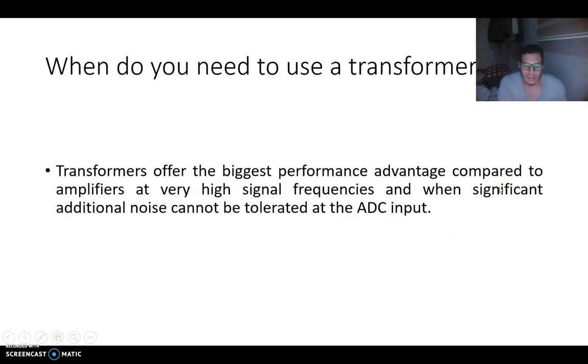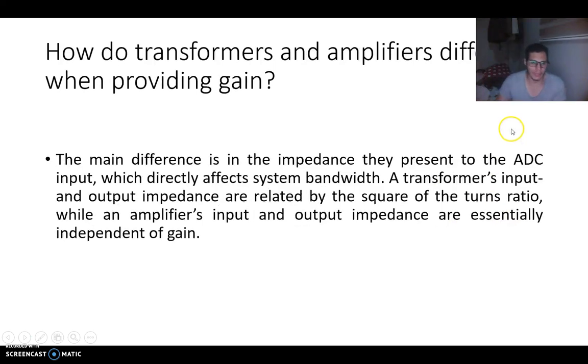When do you need to use a transformer? Transformers offer the biggest performance advantage compared to amplifiers at very high signal frequencies, and when significant additional noise cannot be tolerated at the ADC input.